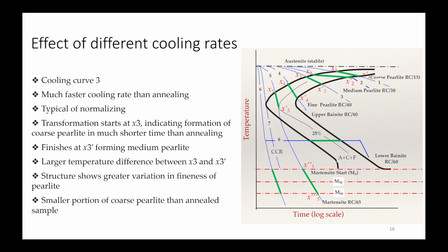Okay, so the solubility is mainly termed using that substitution. We won't be considering interstitial. There is no example of interstitial type of solubility which reaches up to 100%. But in case of substitutional, there are various phase diagrams that show 100% solid solubility. That's what they are trying to see, because there is not much change in the energy as well. Energy is going down, so it is more stable rather than forming some compounds which are changing the energy.